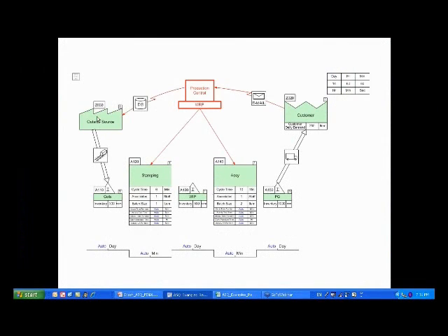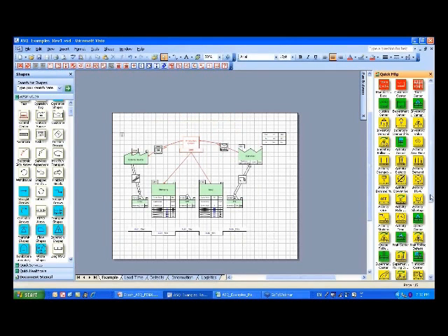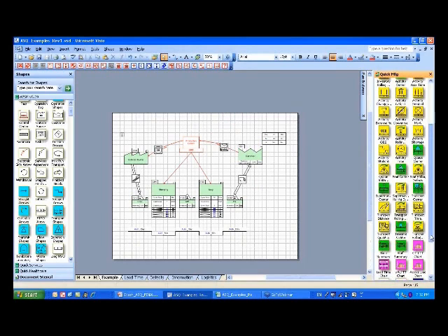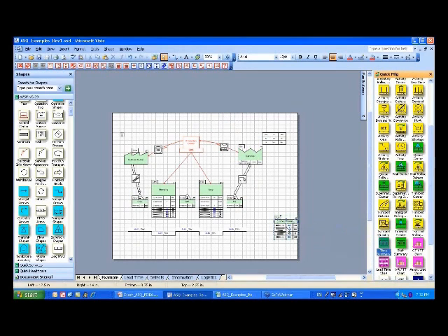So far you can see that we've got the basic manufacturing flow for the simple example. We've got the information flow. We've identified the production time, the customer demand. We've got some order values here, which we'll calculate in a minute. A typical thing you want out of a value stream map is what's the lead time that this value stream represents. So there's a summary box here that we typically use for lead time. And then I'm going to talk a little bit more about what we mean by lead time in the context of this map.